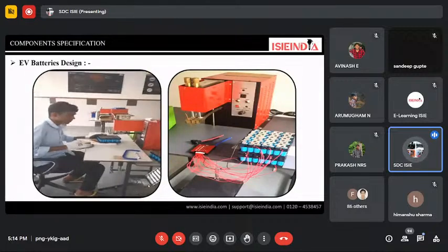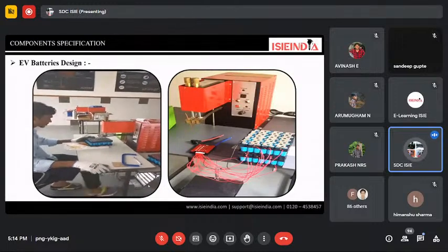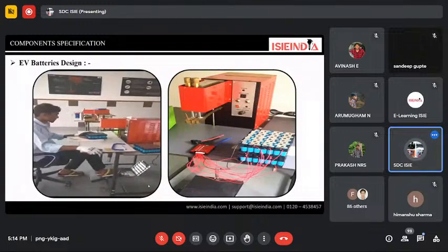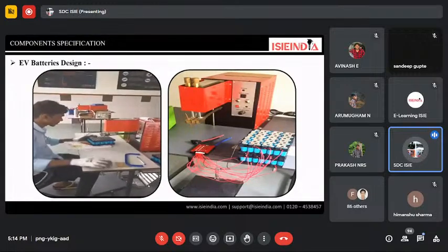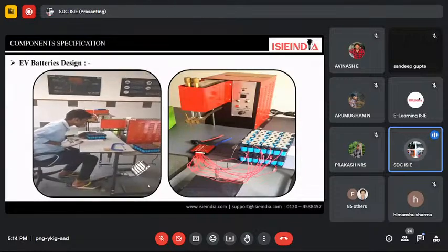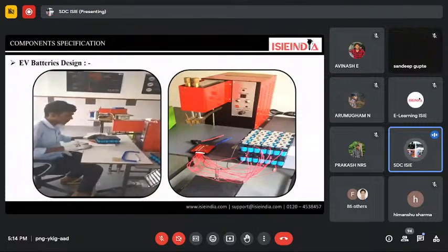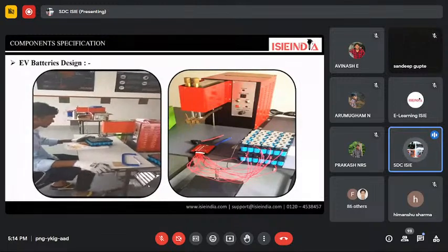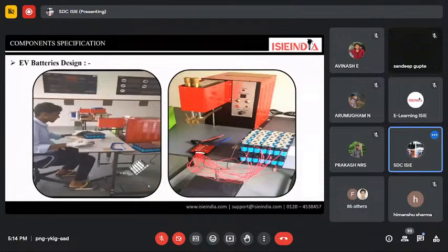Through the spot welding, we can make that battery traction pack, and these wires connect each of the columns, which we can use for the cell balancing techniques along with the power life. It can improve the lifespan of the battery also, and it will help to improve the fault diagnosis of the battery, to identify which particular row we are not getting the desired output when we are connecting through any IoT device, like a Bluetooth connection or Wi-Fi module.